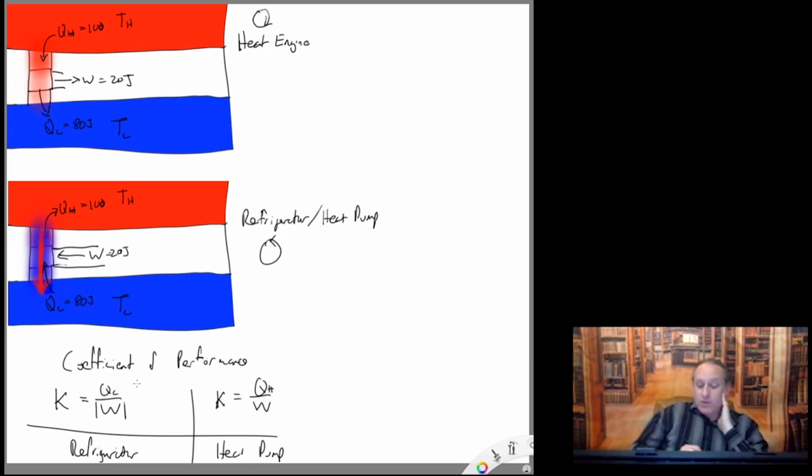Okay, so let's figure out how the most efficient engine would work. The idea for the most efficient engine comes from a French scientist named Sadi Carnot, who devised an engine that, if it's reversed as a refrigerator, would not have any heat leakage. So in that sense, it's a perfectly reversible engine. What makes a difference between an engine that's reversible and one that you can't really reverse? We kind of reverse it, but it doesn't perfectly work.